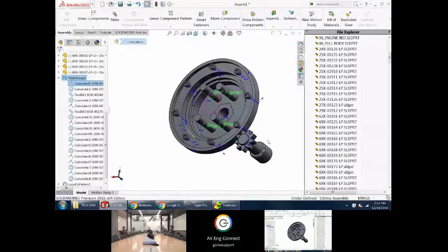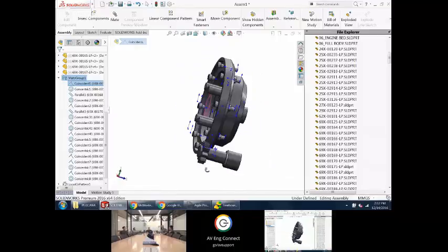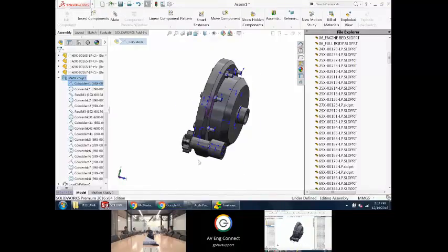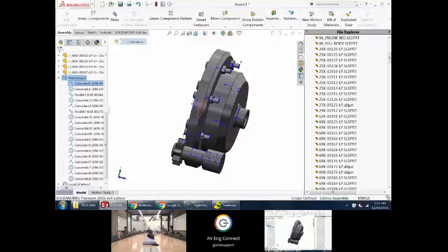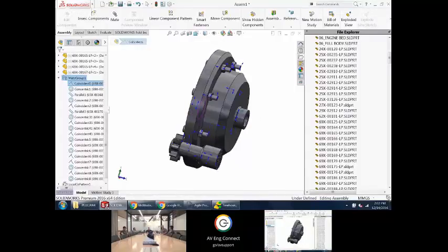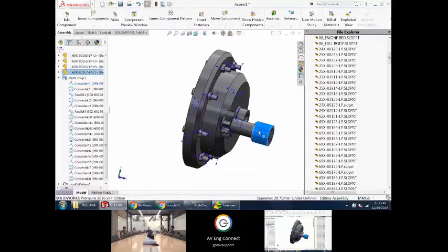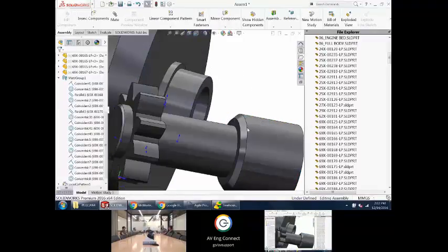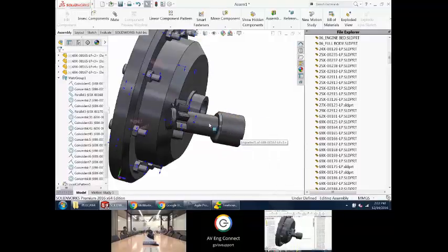Yeah. Now I remember I changed a part so the reference disappeared. So I think it suppressed them because the thing it was looking for was gone. Right. And I had to refix it anyway. So yeah, if you do delete some geometry that a mate is on, the mate will stay behind and just have an error, and you have to fix that error.